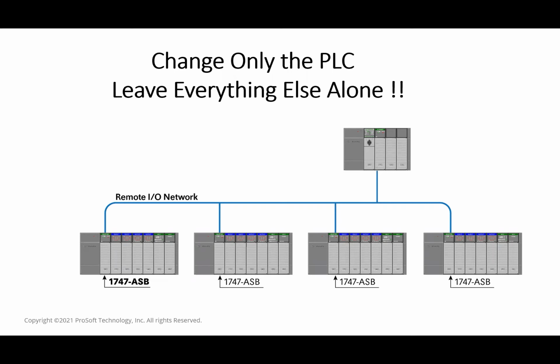Here you can see a SLC with a bunch of remote IO drops. The important thing to note here is this. These IO racks are on a remote IO network, meaning there's going to be a lot of engineering and labor involved if you want to do this all at once. Remember where earlier we mentioned risk and funding, right? Both apply here. A phased approach here would allow you to begin by replacing only the PLC using a gateway configured as a scanner.